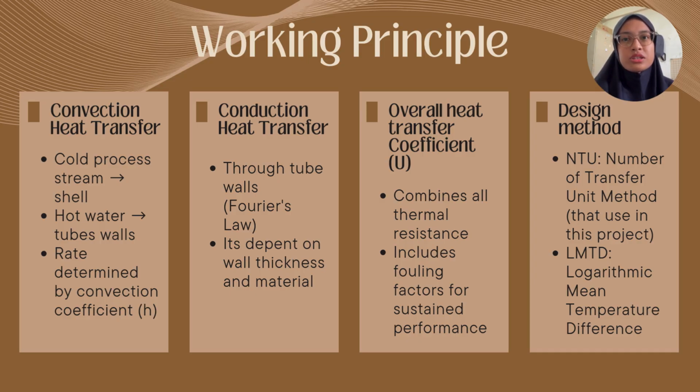Next is conduction heat transfer. It takes place through the tube's wall. Heat flows across the tube material according to Fourier's law, and this depends on the tube thickness and material used. All these heat transfer mechanisms are combined into the overall heat transfer coefficient, which includes thermal resistance and fouling factors to represent real operating conditions.